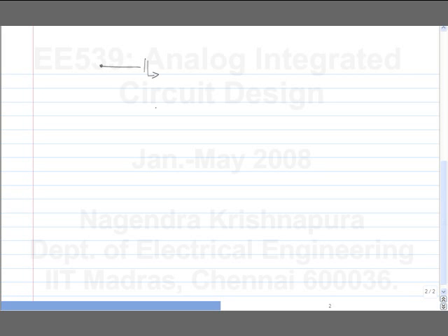if I draw the incremental equivalent, the current source goes away and I have this capacitor, right? This is the load. If I apply certain V_I here, what is the current that flows here? If the degeneration capacitance is C, calculate it and let me know what is the current. You assume that it's an ideal transistor, meaning it has only gm, no gds, etc.